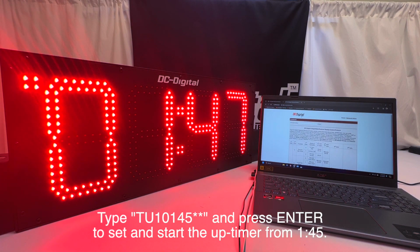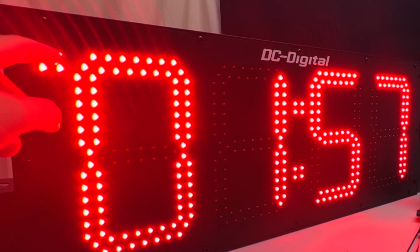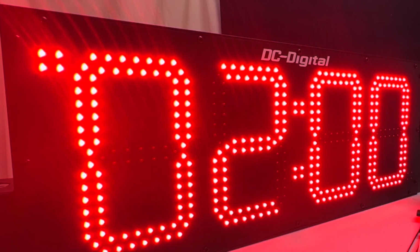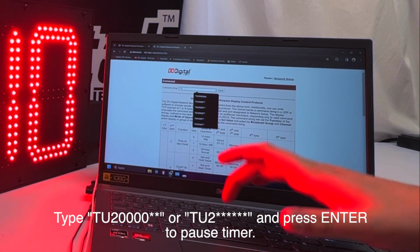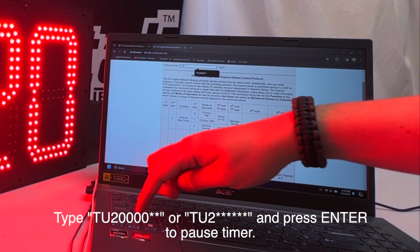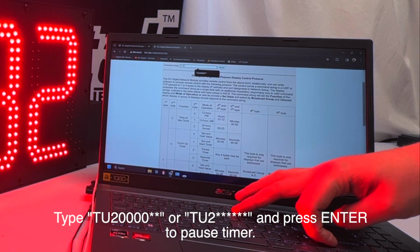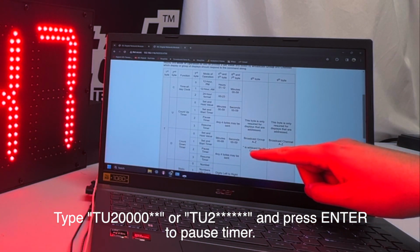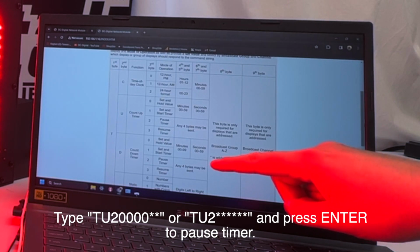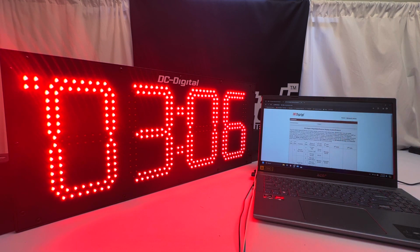As you can see, the display is showcasing the count up feature, counting up from 1 minute and 45 seconds. You can tell by this little dot on the top left side of the enclosure that it is currently in up timer mode. Now I'm going to pause it. We do this by pressing TU2 to pause the timer, and then we add the rest of the asterisks to fill the last 4 bytes sent. We add the last 2 asterisks because we are using the wildcard for all groups. Press enter, and as you can see, that pauses the time.